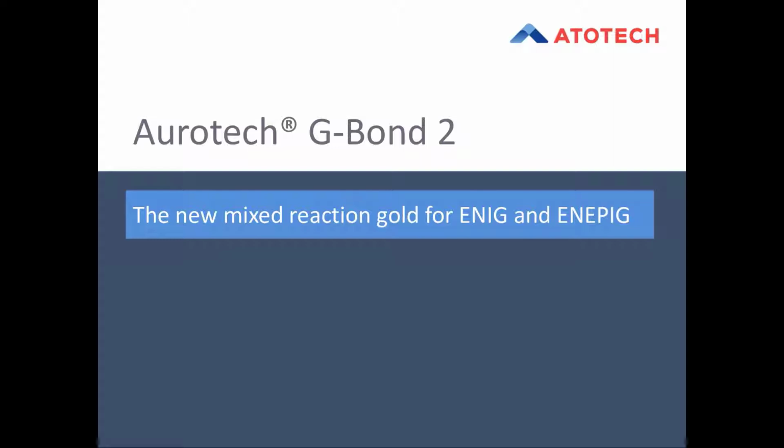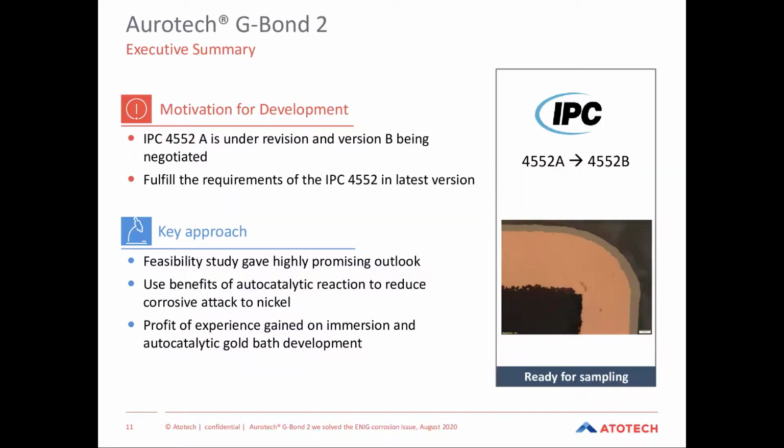So let's go in more detail for the Aurotech G-Bond 2. The driving force or the motivation for the development was for sure also the IPC 4552, which describes the ENIG finish. And in version A, which is currently valid, there are already some descriptions of how corrosion shall be rated to see or to judge if a panel or a finish may be critical in the assembly or not.